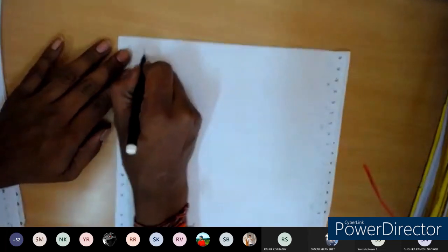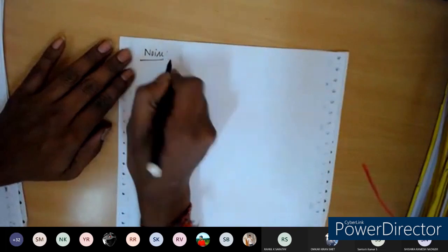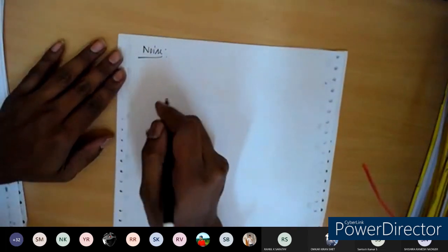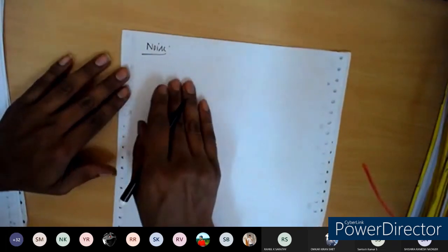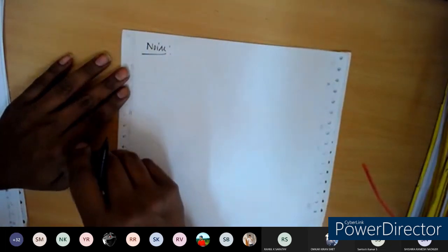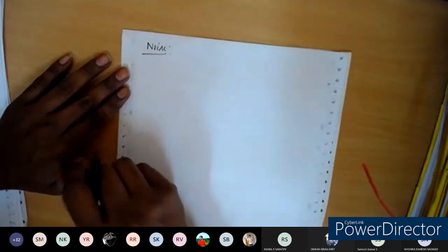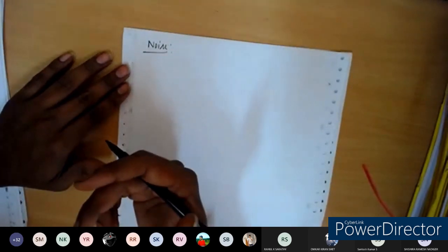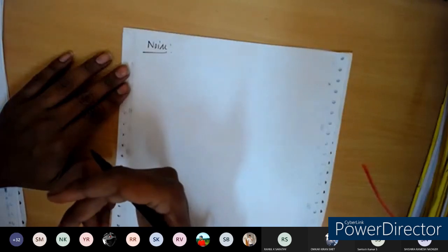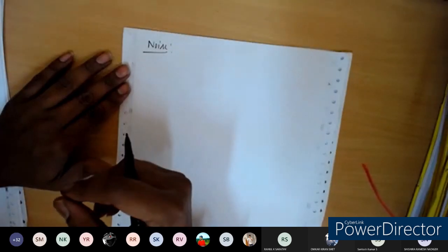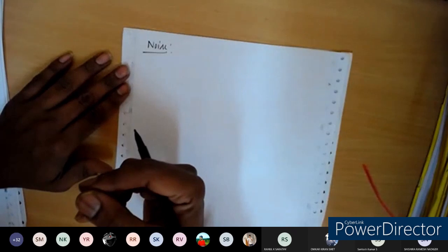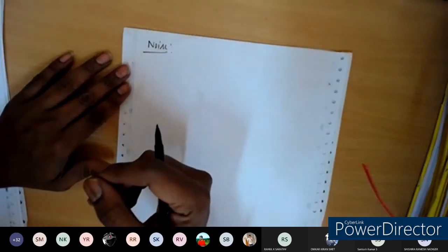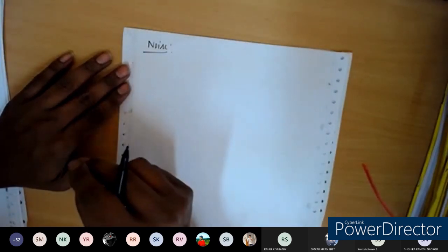That is nothing but the last concept in this model, which is called noise. Noise is nothing but an unwanted signal. Noise will be generated because of many parameters, because of the variation in the atmospheric conditions, or at the front end of the receiver. If the receiver is working continuously, like your mobile phone, what will happen? Your mobile phone will heat up. Because of the heat generation, some noise will be generated. That noise we are going to call thermal noise. Because of the heat, the noise will be generated.